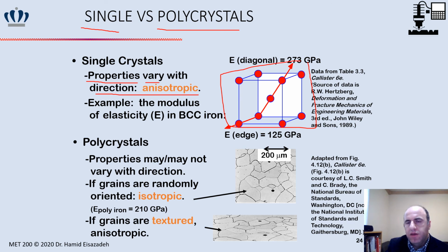One example is this unit cell showing the Young modulus. Young modulus is one mechanical property that we can obtain in the tensile test by pulling apart a dog bone sample. When you stretch this dog bone, you see a stress-strain behavior like that.